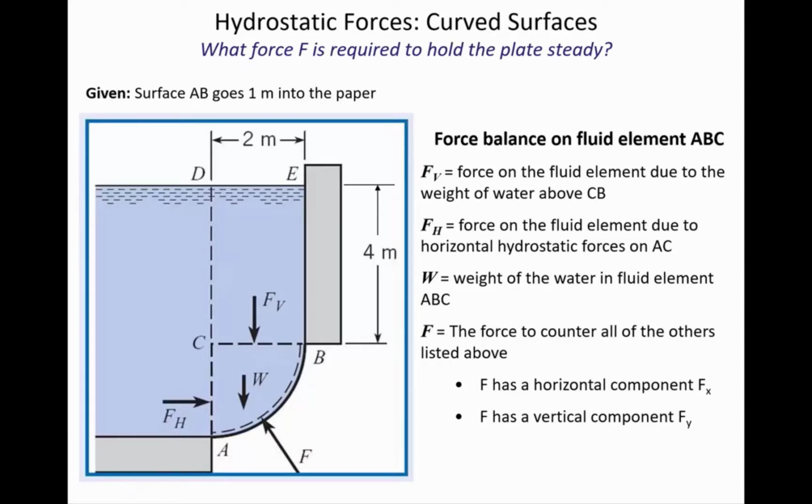So remember earlier I held a piece of paper up and I said the gate is like if you take a flat piece of paper representing like a metal plate and then you bend that and now it's a quarter circle. So you're looking at in the webcam there a quarter circle. And so the vertical projection says, what does that look like from the front? So it's a curve from the side, but from the front it just looks like a rectangle.